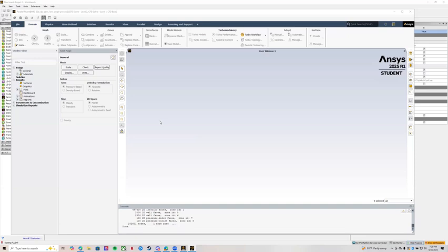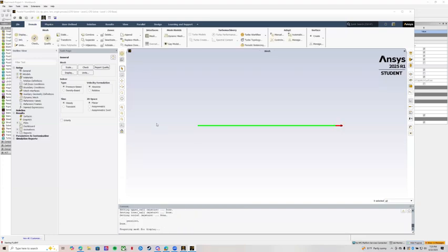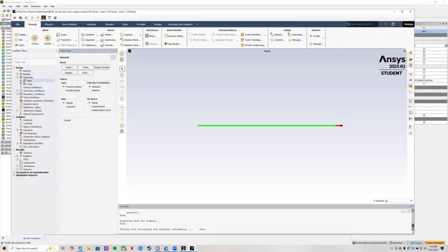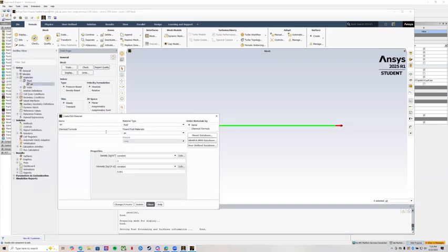Just waiting for everything to load up. All right, so we got everything back. If we just made every fresh one, make sure we're viscous laminar. Materials, we're gonna go to fluid, and we're gonna keep that density at 1. And for our hybrid flow, our conditions were density of 1, and our viscosity was 1e to the negative 4.